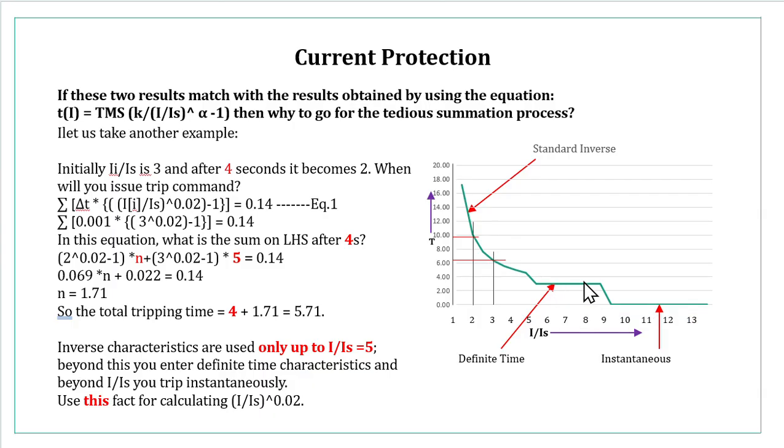And moreover, this is adjustable. If you find that the motor is taking longer, then you can set the value to something higher, right? Give it more time. Otherwise, unnecessarily, you will be starting and tripping a motor and never start your real job. So friend, we have a definite time delay as well as instantaneous. When current is very high, it means it is not really starting current, it is something else. There is fault and therefore you must trip it. Then you trip it directly.